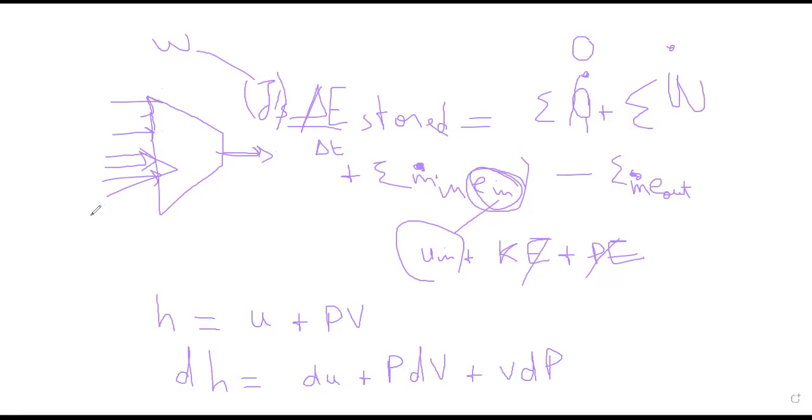You know that for a force the work is force times distance. And we know that the force is a pressure times an area. So when we do PA times D, we can say that the work of pressure is pressure times volume.